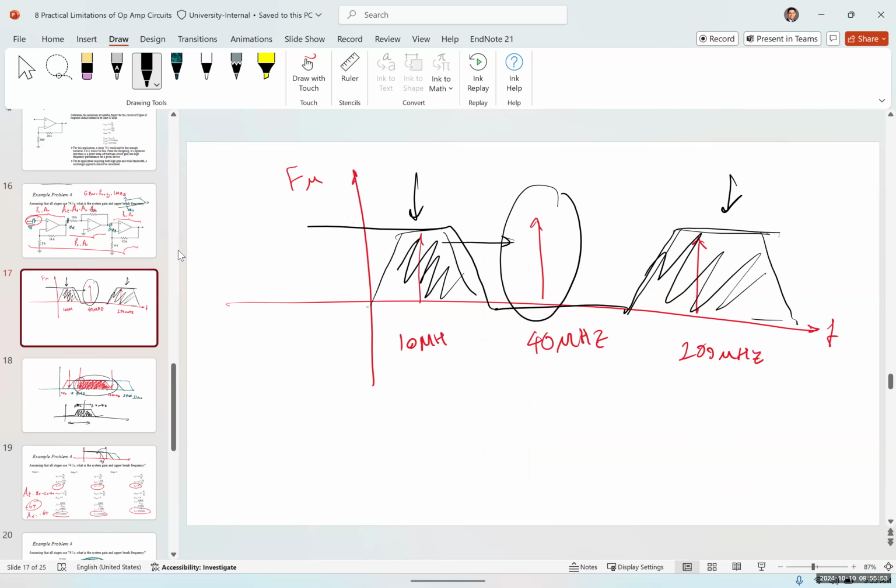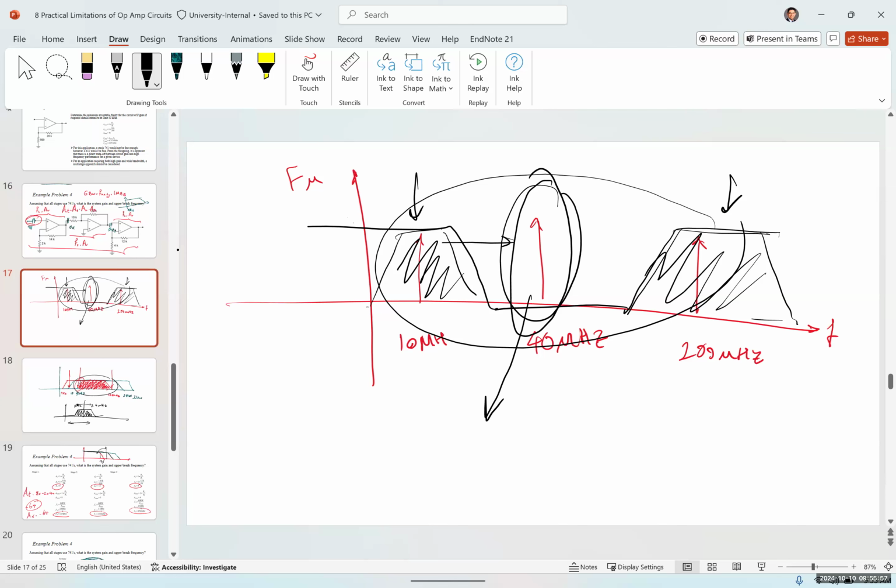So what we do is we use this notch filter. And the good thing about these outlet frequencies, like the 60 hertz, is that they are fixed frequencies. So we would add a notch filter to these type of circuits to filter out certain frequencies, like 60 hertz or something like that. But if you have a variable frequency, that's going to be with what we call adaptive filters. It's going to be very expensive, much more complicated. But this is an example of a notch filter.